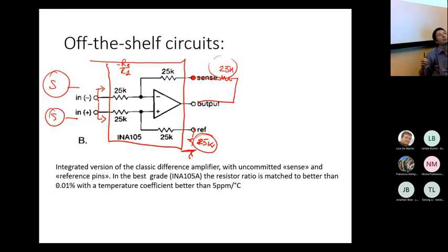Okay. Remember that in a typical configuration, when we want to amplify voltage signals, we also want very high input impedances in order to minimize the voltage divider effect across the output parasitic resistance of the source.